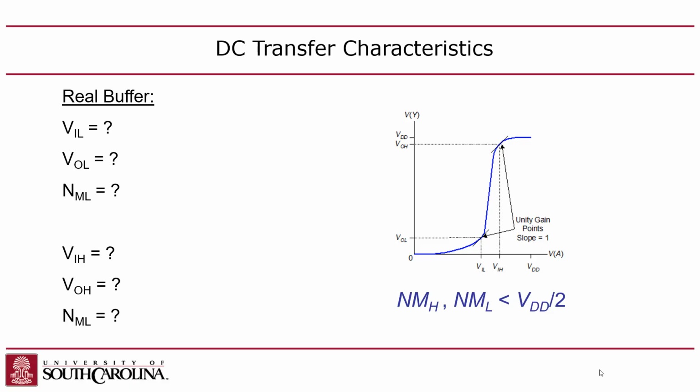So you can see that because VIL is greater than VOL, this gate is kind of protecting you a little bit in terms of the noise on the intermediate wire, right? It's more tolerant of higher inputs for 0 or lower inputs for 1 than it is in the way that it actually puts a value out. Does that make sense?